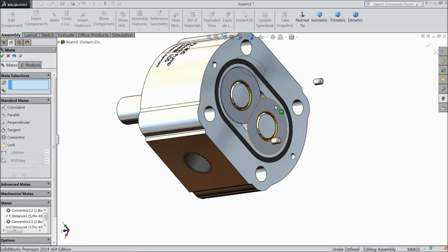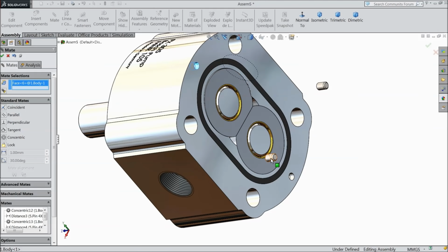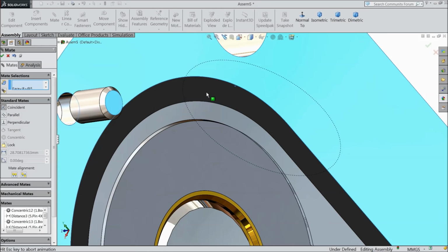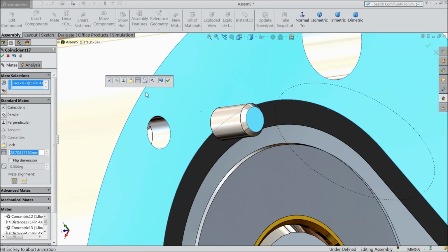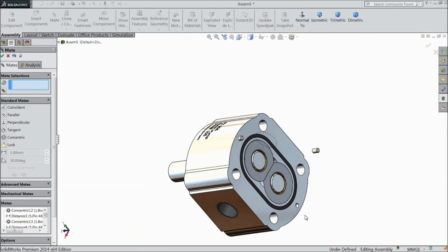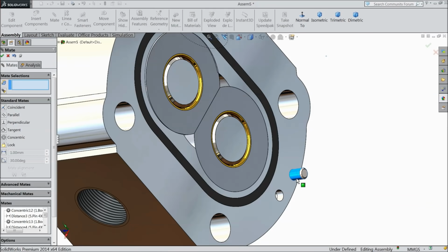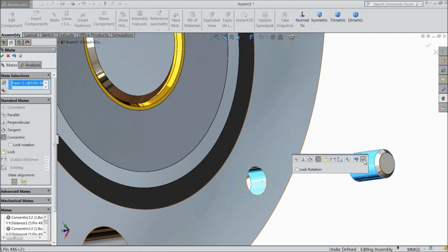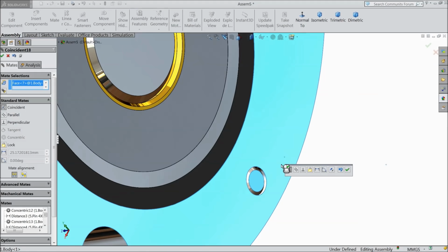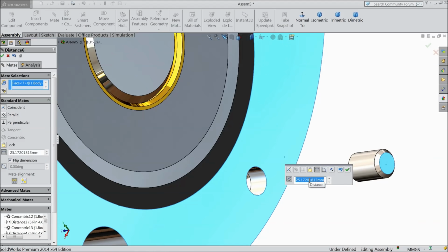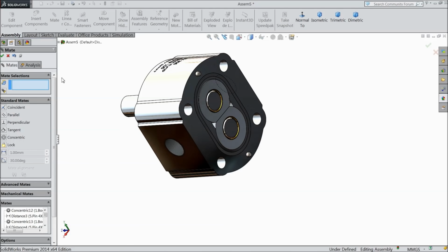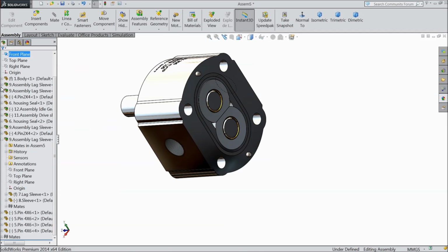Okay, now bring both the pins another direction, select this. Okay, this face and this face, 3 mm, and the last pin drag it here, concentric relation, and make the gap 3 mm. Now pins are fixed. Now we will browse our next part,